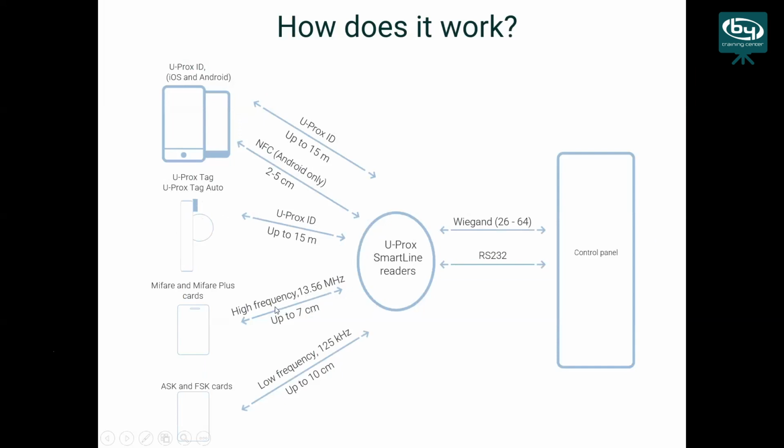Also, it has MIFARE technology. The MIFARE cards work at 13.56 megahertz. Also, we have the low frequency EM frequency, which is 125 kilohertz, and this technology is also operational in U-Prox SmartLine readers. As you can see, we have 4 different technologies.